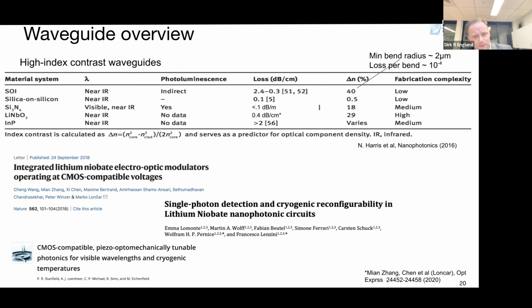Well, not necessarily, because a lot of the time, for example in our case here, we're interested in the loss per gate operation rather than the loss per distance. So per centimeter should not be the metric. Generally, you can take that, multiply it by the length of your device to get an overall dB figure, and that's generally the more important thing to compare between different waveguide platforms.